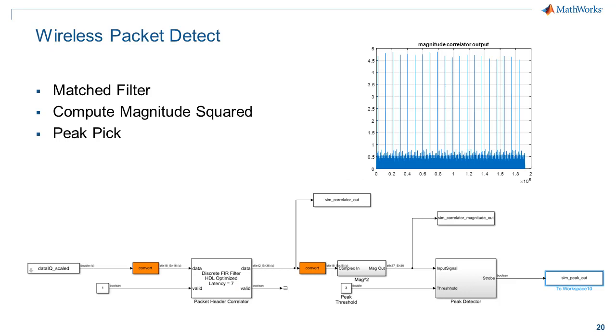And if we look at what we did on that last example, we really pulled it all together. So we started off with a matched filter that had to be implemented. We made sure that we quantized the input to an 18-bit word length, which is going to map well to an FPGA. We did the FIR itself full precision, so we don't expect there to be any mathematical error coming out of the FIR filter.